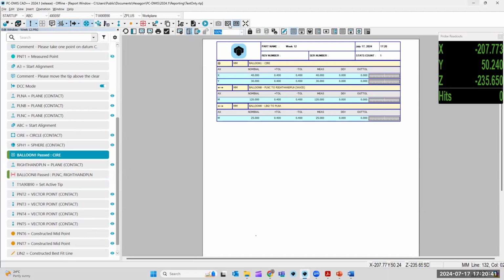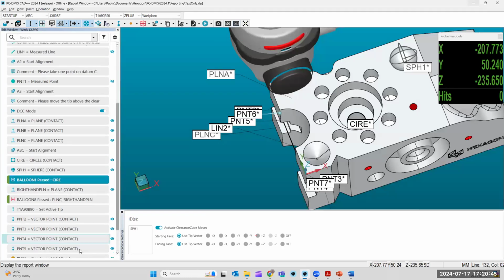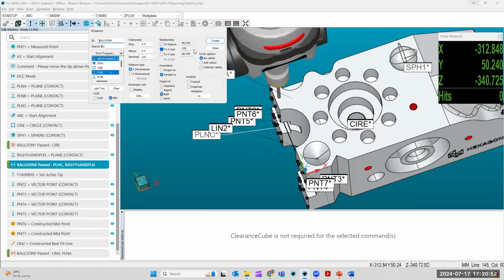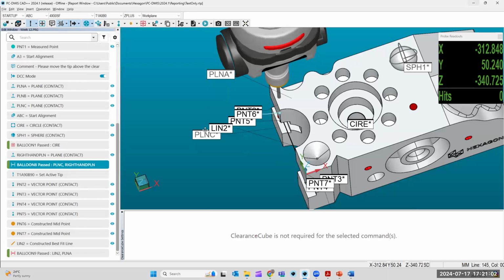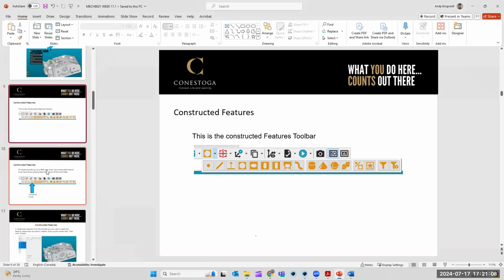Okay, so that is standard distance and location dimensioning. They're pretty basic for the most part. If you feel like you're doing it wrong, play with the 2D, 3D, and the X and the Y features until you get the correct nominal, and make sure your tolerance matches your drawing, because not every feature is going to have a 0.4 tolerance. Okay, now I got to get to GD&T because this takes a little while, and this is where our lab comes from for next week.